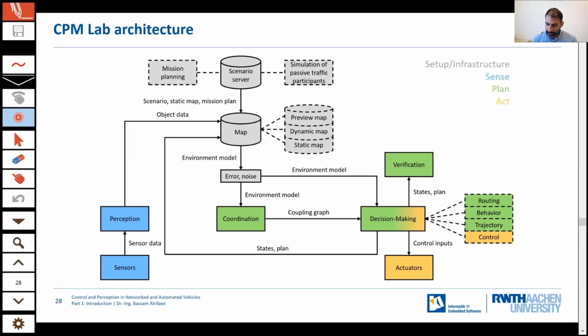So the next level is the trajectory. If you have taken a decision about the behavior, now I would like to take over the truck. The trajectory is how to take over. So it is more specifically the X, Y, where you should be in the next states. The orientation belongs also to the state, and also what's important in the trajectory, the time. So be at position X, Y at time T.